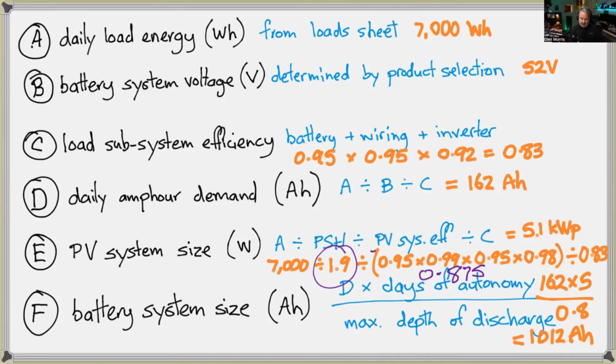The last part we did was the battery sizing. We did this yesterday, and we had to decide how many days we want of backup, how many days of autonomy. So weather here in Melbourne at the moment is terrible, and so hardly any solar came in today. So we didn't really recharge our battery system. So we needed a battery system that can cope with a weather cycle. That's a good sort of target, an average weather cycle.